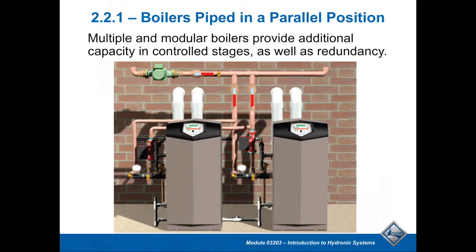You have to watch the temperatures you would potentially be running in those. If you're in excess of 140 degrees, which is generally the maximum for PVC, the PVC tends to create problems for you, with chemicals leaching out of the PVC. You've got to be a little bit careful on that.